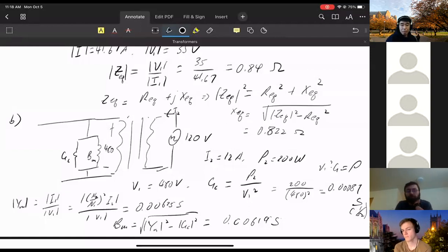Does the propagation time of a signal over a long transmission line affect the apparent phase difference? Not really. GPS signal is correct to about 1 microsecond or so. And for grid applications, an accuracy of a few microseconds is good enough.